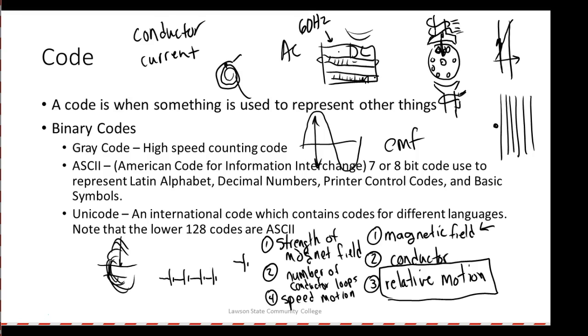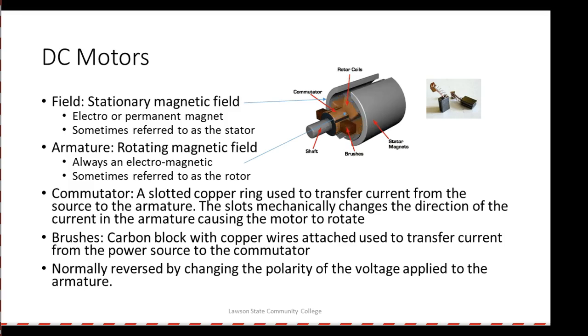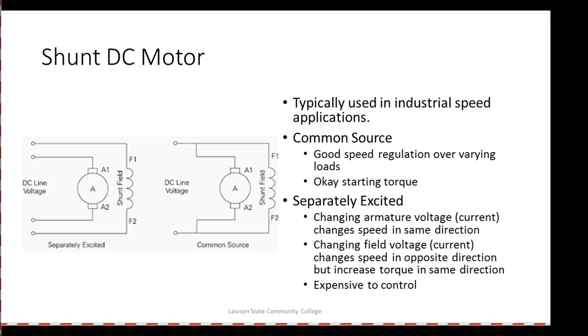A DC motor, how do you create an electromagnetic field in that rotor? Well, you've got to take it in there, right? You understand? So the way a DC motor works is we have a unit out here. So a DC motor, we have to have brushes. Now the field can either be a permanent magnet, but at least one of the fields of an electrical motor has got to be an electromagnet. So if I put DC into this thing, this guy would come up and it would just stop when it lines up, right? You understand? Unless we do what? Unless we switch the magnetic fields.